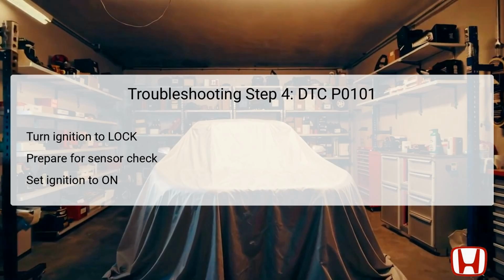Begin by turning the ignition switch to the lock position, ensuring that all electronic systems are completely powered off. Next, quickly turn the ignition switch to the on position, 2, which will power up the vehicle's electrical system and allow access to data readings without starting the engine. This preparatory step is crucial for isolating the MAF sensor's performance measurements before proceeding further, which will allow for a clearer diagnosis of the underlying issue related to DTC P0101.